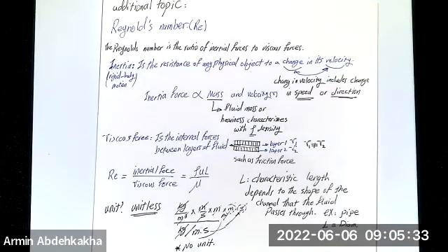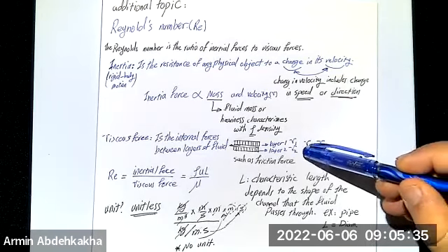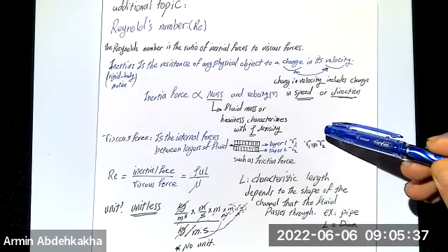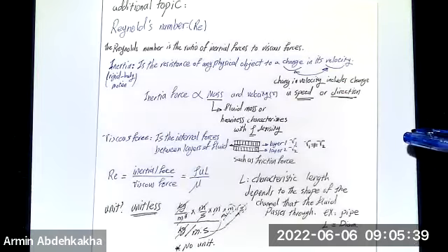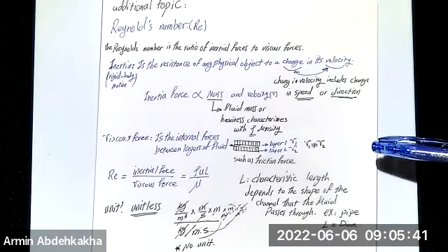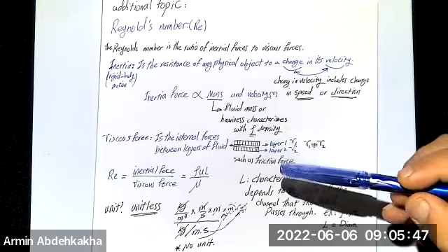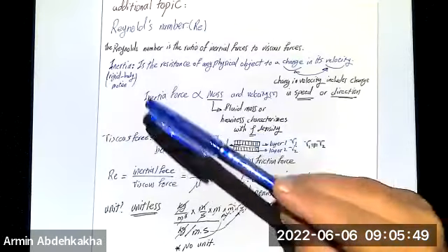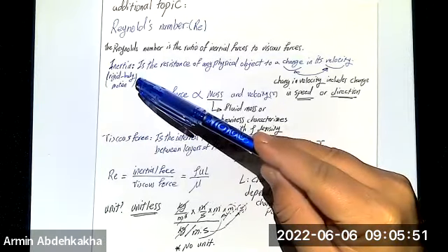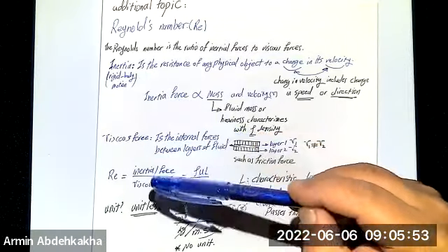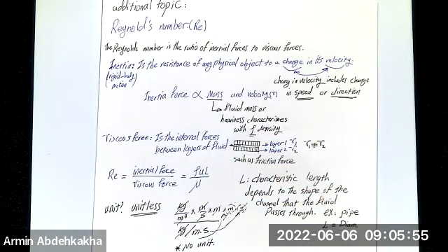And also at the top plate, when you have two layers of fluid that move together, or one of those is pulled, then the layer of fluid close to it, because of the no-slip boundary condition, sticks to that layer. So it's very important to know that these two forces are the main forces in fluid mechanics, and it depends on how much these two are different.